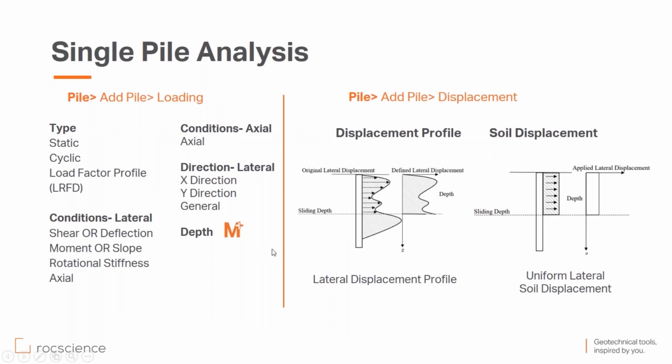New feature alert again. Once you have your pile property set up, you'd like to add your pile loading. So you can have static, cyclic, or LRFD. You can have a load factor profile in your loads. The conditions, there are many. You can add your load in different directions, also moments.